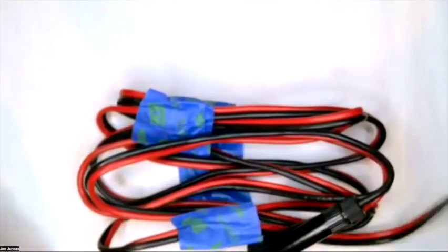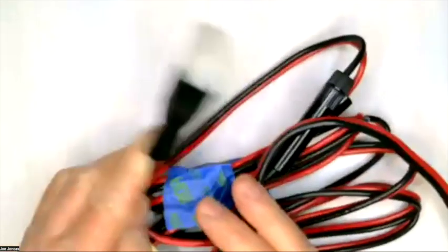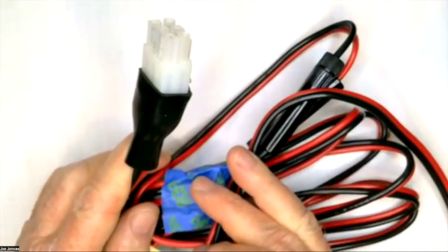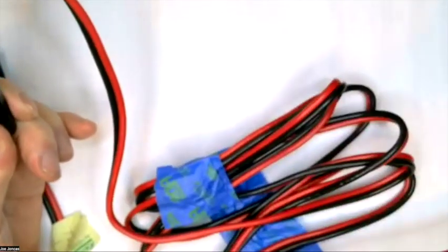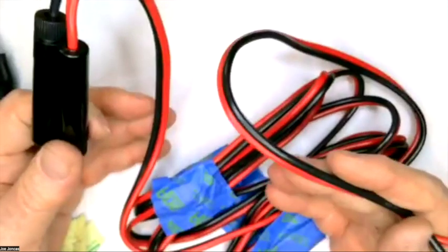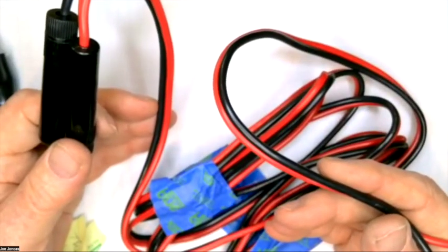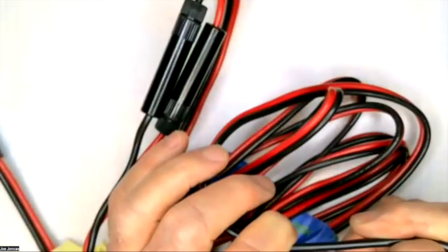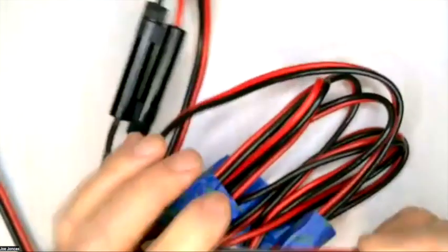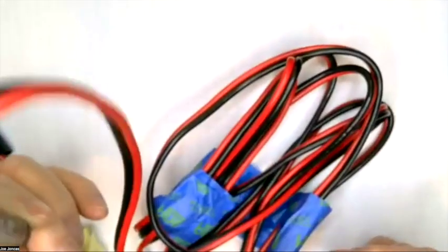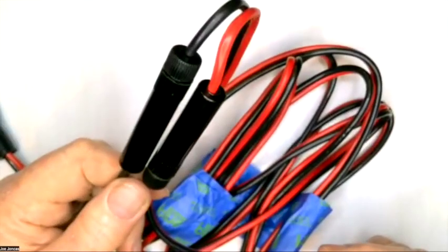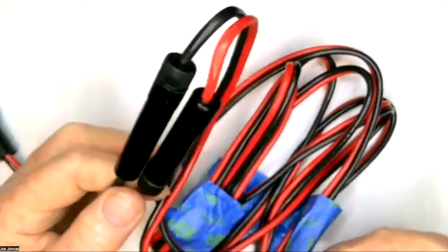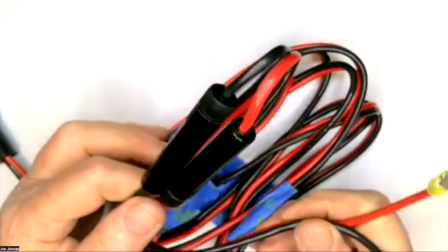If you have these hooked up to a 12-volt battery and this whole thing stretched out through your car and something shorts at the ground, with the fuses here, they're not going to blow. What it's going to do is burn up this cable and your car. These things need to be at this end by the battery. And don't use this style of fuse. I can't tell you how many fires.